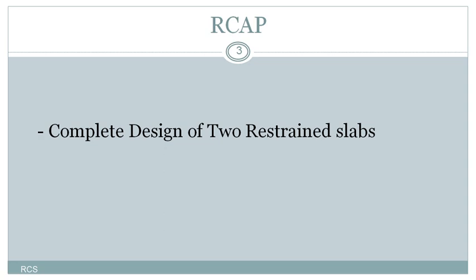As you know, we have divided our two-way slab into middle strip and edge strip along the x and y directions. In those areas we have to calculate the reinforcement. And similarly we have another provision of reinforcement. As our slab is a restrained slab, we have to provide reinforcement in the corners also. That is called torsional reinforcement. Those torsional reinforcements are provided based on the codal provision at the corners of the slab in order to prevent cracking.